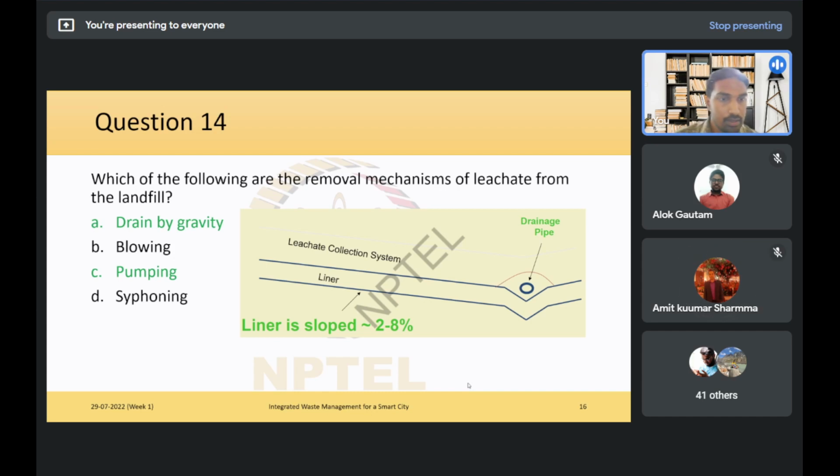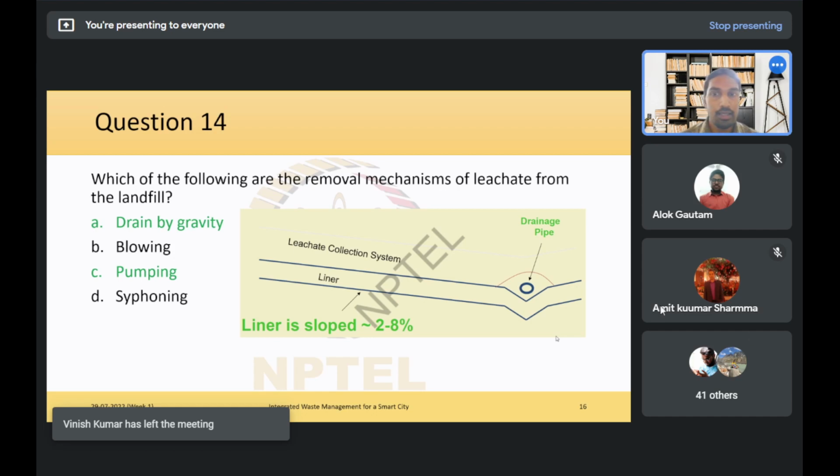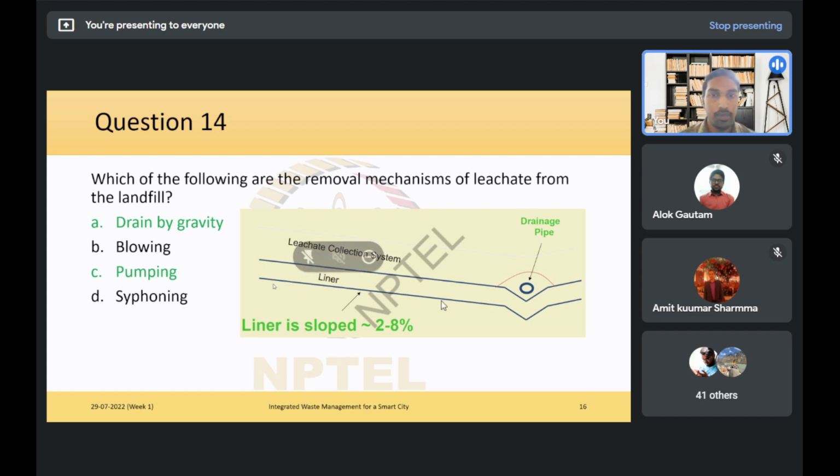Okay, there is a question on the chat. Will we give a slope to the soil under the liner? The soil under the liner, we are not going to be worried about it. We are preparing the liner. The liner is going to be the bottommost point of our landfill site. So we compact this liner layer, and the soil below it is going to be the natural soil, whatever is there. So we are not going to be worried about that part.